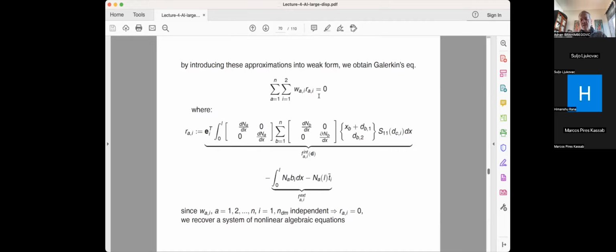In fact, by using this interpolation, you come up with the final product of finite discretization, which is a Galerkin equation, which expresses the equilibrium equation in the weak form in terms of the unknown parameters of a displacement field. And the residual R(a,i) in direction of the axis xi, for any arbitrary value of the virtual displacement at the free nodes, has to be equal to 0.